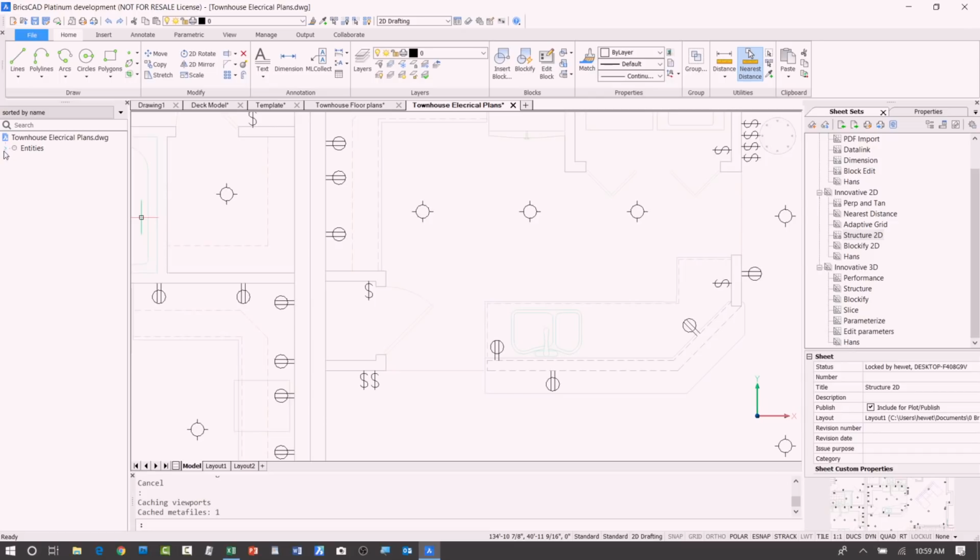And in this drawing, I'll just use the default structure sorting. I can see my various entities, and I can tell right away that this is probably not a really good drawing because I've got all these entities, 700 entities on layer 0. That doesn't look really clean to me. And I can see that I've got other layers here, but I don't have a lot of geometry on them. So the structure panel is just great anyway with that.